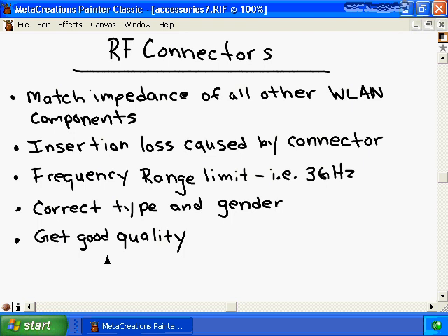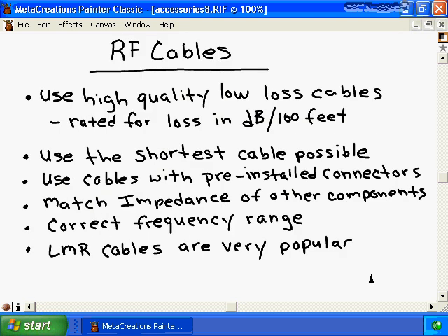Again, this is a focal point of where you're connecting your antenna to other accessories. So you don't want to scrimp and try to save a few pennies with this connection, because you don't want to have RF signal loss at this point. And make sure you get the good stuff. Splurge, have fun. Now, if you remember earlier, I'd mentioned that RP, or proprietary type connectors, were created in response to the FCC ruling Part 15 to require that the connectors either be proprietary or be installed by a professional. Well, there's a cable that lets you get around that a little bit.